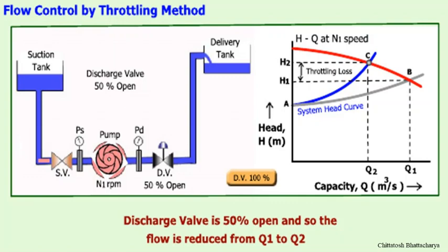System resistance is increased on the suction side, and also on the discharge side. So it increases vibration and corrosion also. Therefore, it will also reduce the safe operation and increase the maintenance chances, so it reduces the lifetime also. So variable speed drives are a better solution than throttling in terms of energy efficient operation.